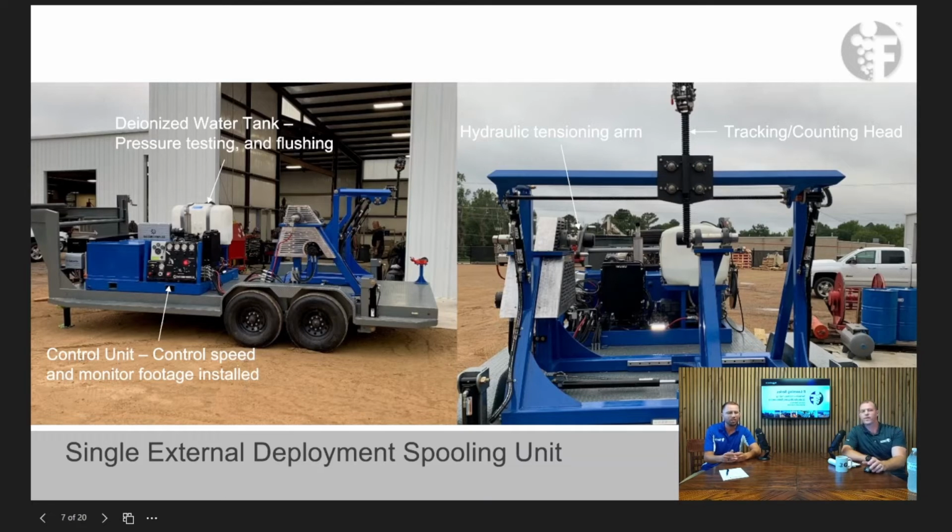The big thing is the guy on the floor is also watching, making sure your string is not getting pinched, like from the slips or something like that. That happens. So you've got 2 guys, one backing up the other. He's helping the rig crew take that cap tube and attach it to the outside, and making sure everything's centered. That's really important, making sure your tubing's centered so your string doesn't get pinched. And then from there, running in hole.